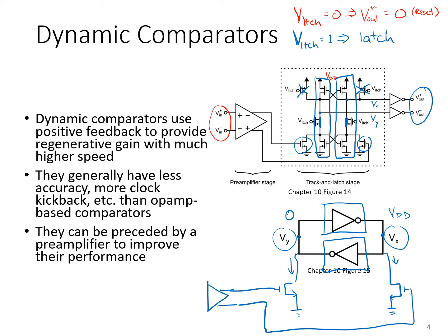So ultimately resulting in a differential logic signal whose polarity depends on the sign of the applied differential input voltage. So there's several advantages of comparators like this. By taking advantage of the positive feedback, you can realize a very large gain, and there's potentially much less power consumption than in an op-amp circuit. You'll notice here there's no DC bias currents flowing.